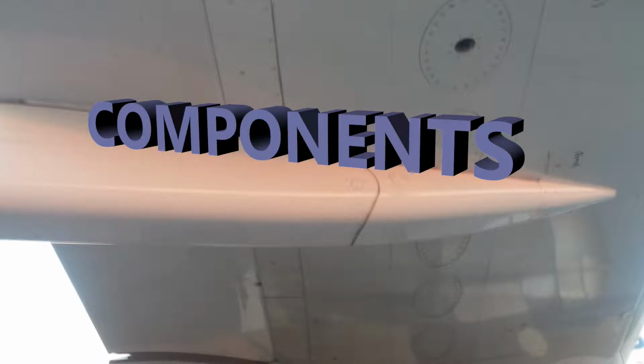All right. You're also going to find there are some plug connectors in the wiring, and those are going to be located in each of the wing tanks. Okay, and there are different kinds. You've got your shorting plug connectors and your fuse plug connectors. So those are at the wings. Your fuse plug connectors in the wiring are contained in each of the wings and also in the center tank. Okay, so that's for the fuse plug. The shorting plug is found only in the wing tanks.